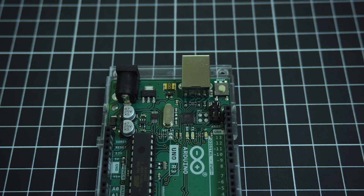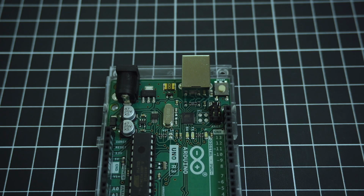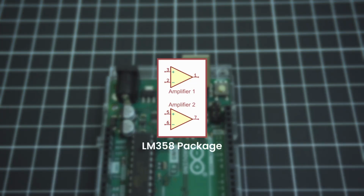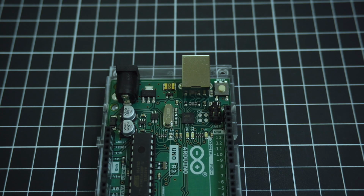Another key component on the Arduino UNO board is the LM358 operational amplifier. The LM358 includes 2 internal amplifiers within a single package. One amplifier is responsible for automatic power selection between the USB supply and an external DC adapter. When both power sources are connected, it functions as a comparator, monitors the voltage levels, and selects the appropriate source